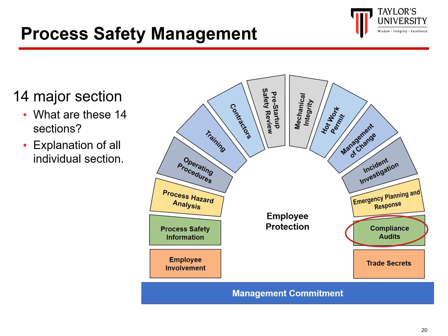Under the audit section of the PSM standard, employers are required to certify that they have evaluated their compliance with the standard at least every 3 years. The recommendations from the audit must be followed. The audit report needs to be retained as long as the process exists.